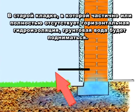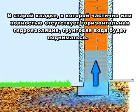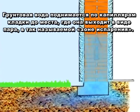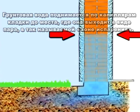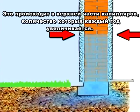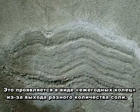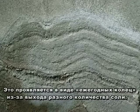In old masonry that lacks a horizontal moisture barrier or where it is partly rotten, ground moisture rises into masonry. Ground moisture in the capillaries of masonry rises to a point where it oozes out as water vapor at the so-called evaporation zone. This results in the capillary head in masonry, which grows a little every year. It may be manifested as annual rings caused by different degrees of salt efflorescence.